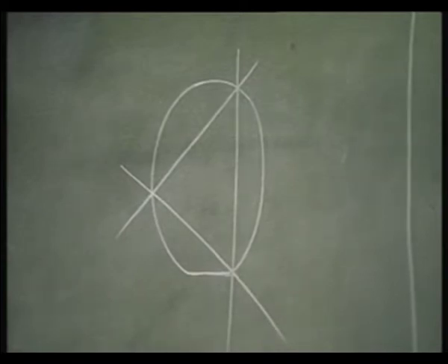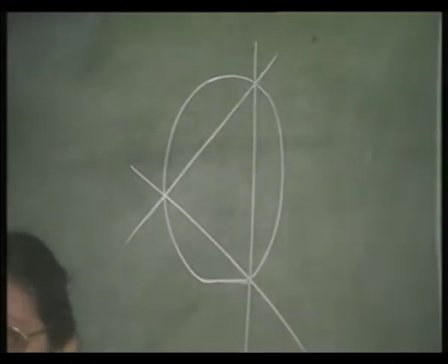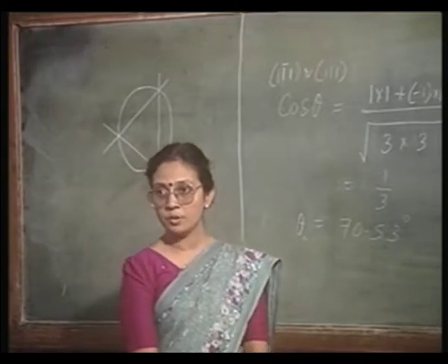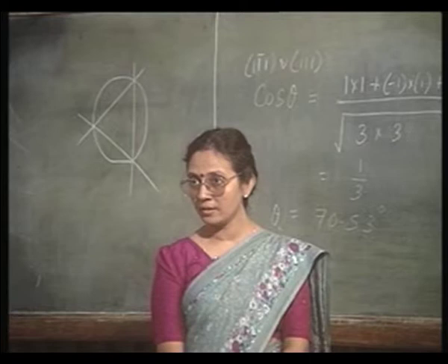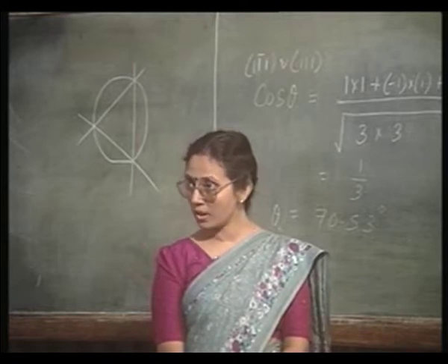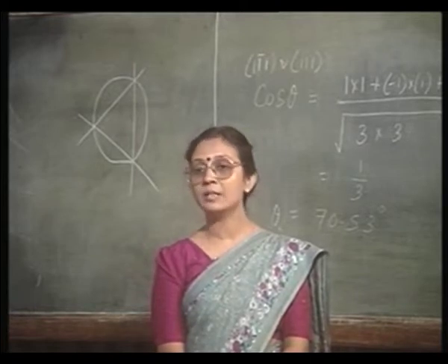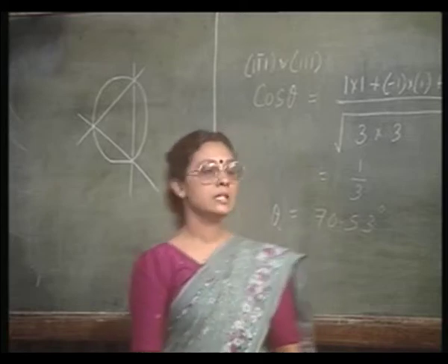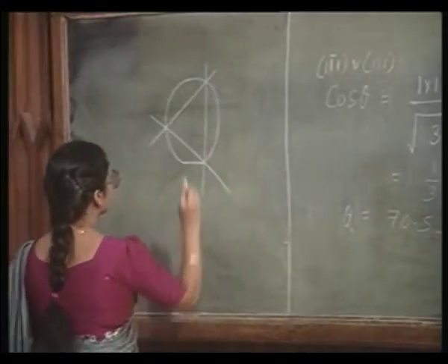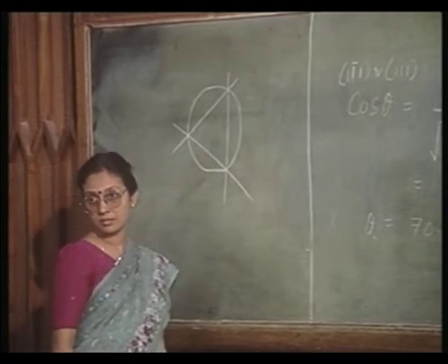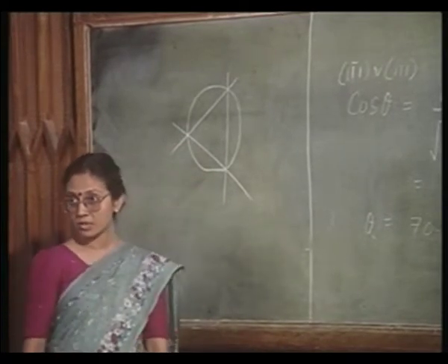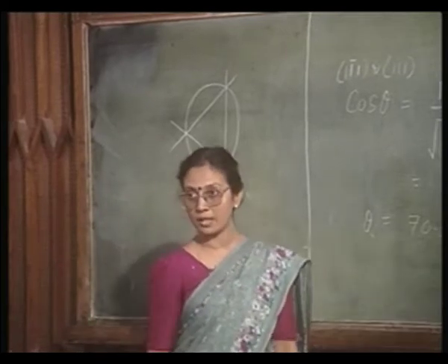It is going to be like this. Remember, the 111 plane, it is bound by the 3 110 lines, and they are constituting a triangle, and the angle between any two 110 lines is not 90 degrees, but 60 degrees, right. It is an isosceles, sorry, it is an equilateral triangle.